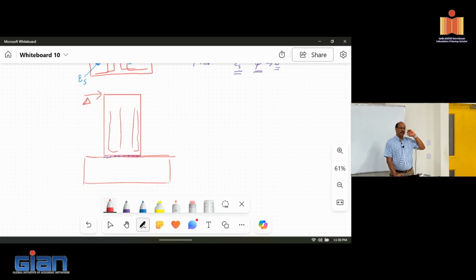Let's not put anything across, except that you know there's some gravity load sitting here. What would happen if I just push on it with the displacement? Again, I want you to think about crack pattern and the force displacement. There's nothing crossing, this wall panel is sitting here with a vertical load on it, and I'm just going to keep pushing it with the displacement.